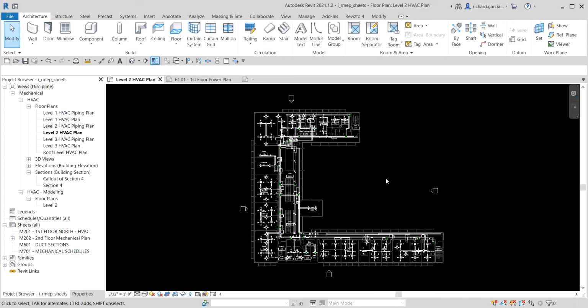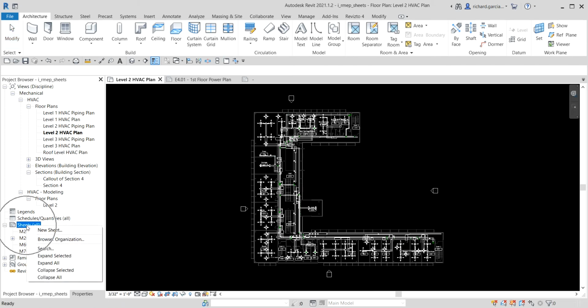So anyway, in this exercise, after learning the basic stuff of title blocks, we're going to create a sheet and modify its view properties. And then we are going to place a plan view and a section view on our sheet and specify the print option if you want to print it. Okay, so let's try this one out. The first thing that we're going to do is create a sheet and modify its view properties. You know already how to create a sheet, right? You just need to right click the sheets here and then select new sheet.